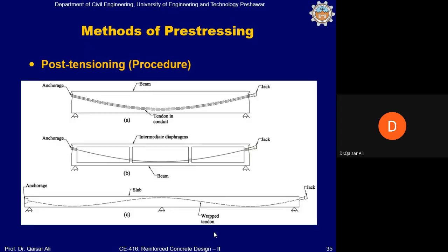It will be like this. This is an anchoring device, with this desired profile which is to be used after the design. Okay, and this is the jig. When concrete is poured inside the formwork, the steel wires or tendons are in unstressed condition. Then after concrete attains its full strength, the cables or wire is stretched with this jig and also anchored on this side. This is anchored already on this side.